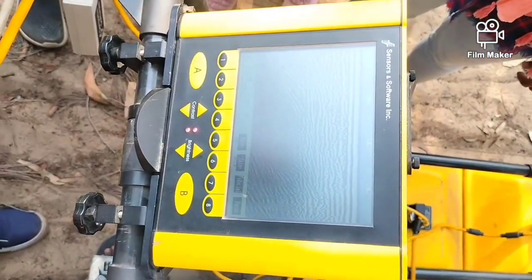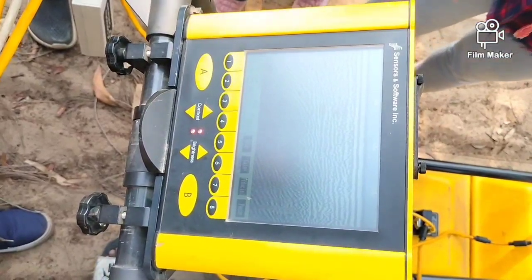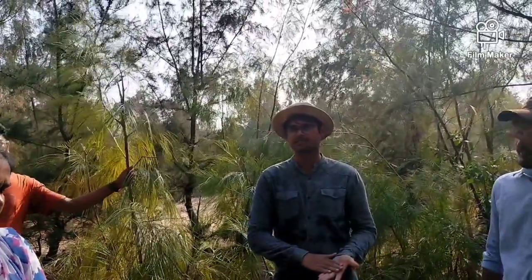Does anyone have a notebook here? What do you guys think you can use GPR for? First we have to select some location wherever we want. Yes, but what do you want to look for in the subsurface? For constructing a road or something, we can get to know what is under the road. Yeah, like we have to identify utilities, because if there are utilities and you just stick down there, you might rupture things. Yes, so you have to confirm what's inside there so that the construction won't be affected by something in the subsurface condition.